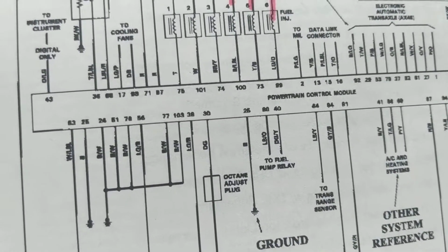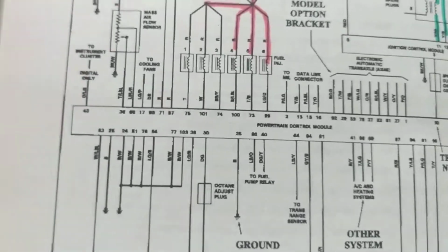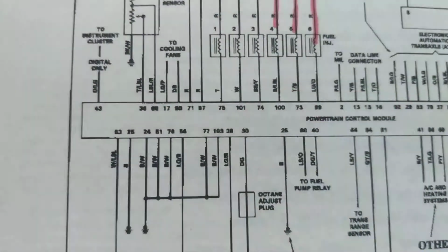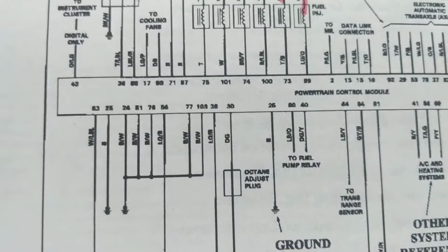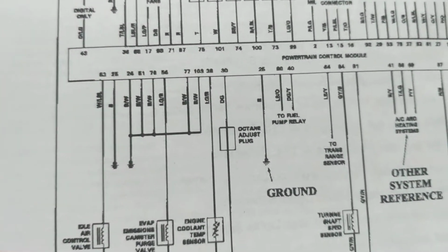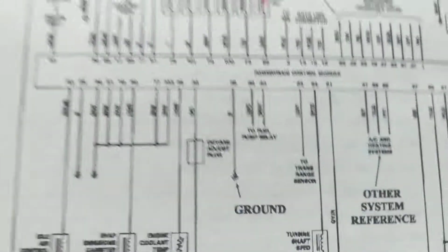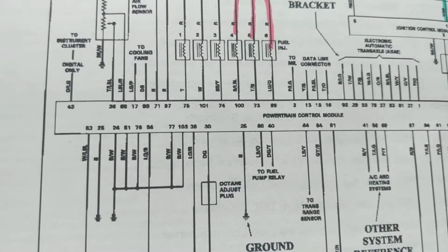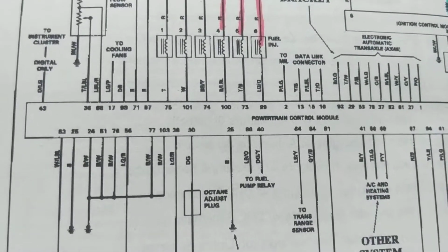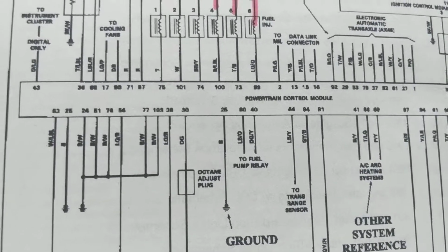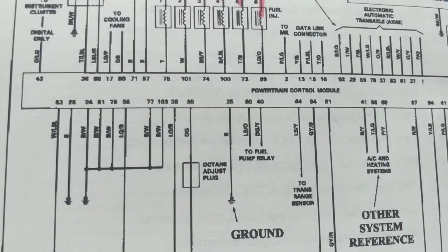The throttle plate allows more air to go into the air chamber, into the intake manifold, which is obviously the engine. The PCM has to decide how much fuel to give, dependent upon how much air is coming in. More air, more fuel. Less air, less fuel.